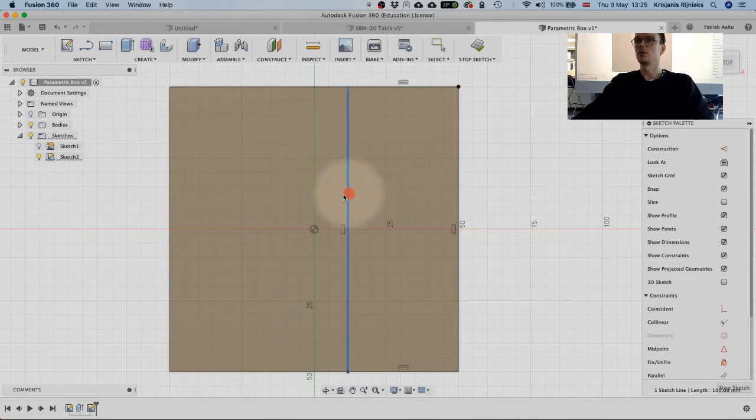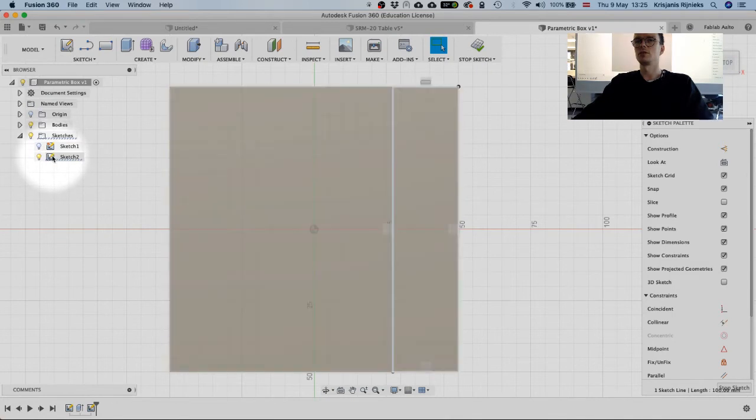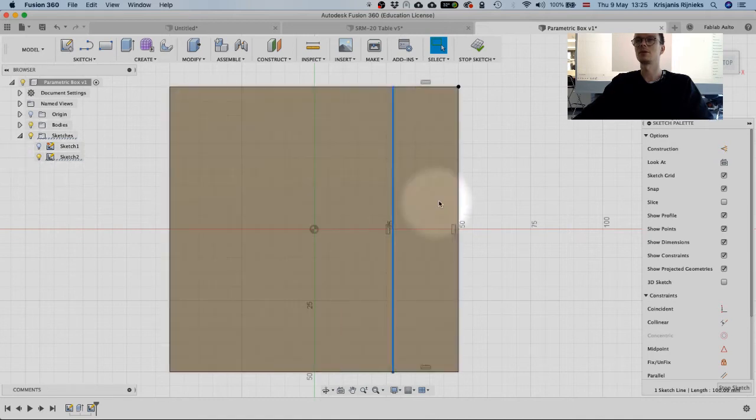Now, you'll see you can drag around only this line. So this here is a constraint, and this here is a constraint. If you click on the individual ones, you can see that this is perpendicular to something, and here that this is coincident to the line, and so on. We also need to achieve a state where this is fully constrained, when it has this little pin in the top left corner of the icon in the browser.